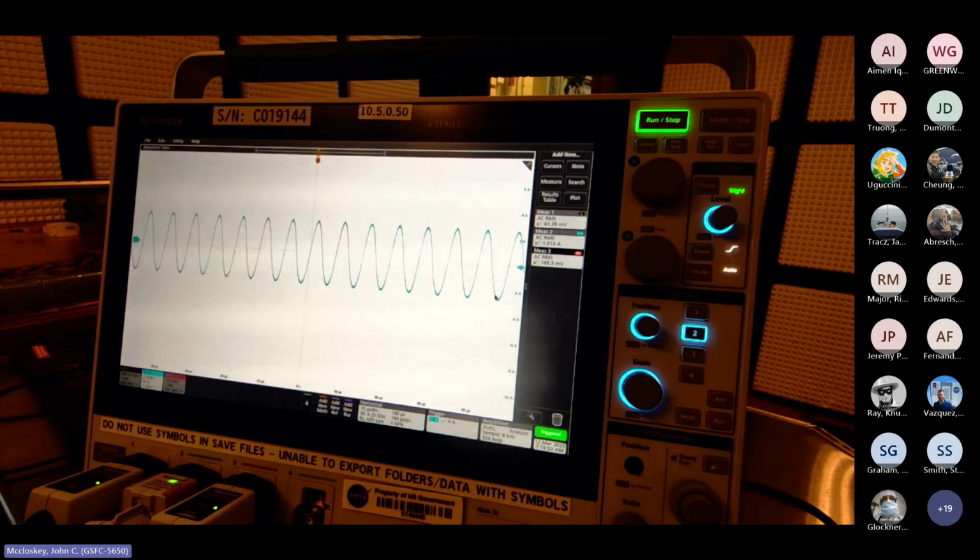So the resistor itself may have some inductance that starts kicking in. The wiring, just the loop of wire to get us from the transformer to the resistor, is going to have some inductance that may start affecting things. At 100 hertz, I wouldn't expect that to be real significant, but above about 10 kilohertz, probably. About 10 kilohertz is where some inductive effects can start kicking in. So when you're relying only on the pre-calibration step, the maximum current that you can get may not be quite what you think it is.